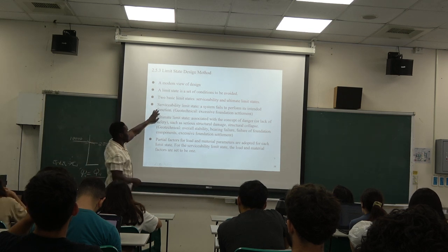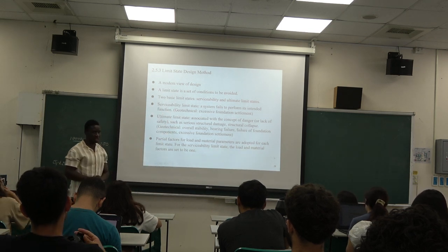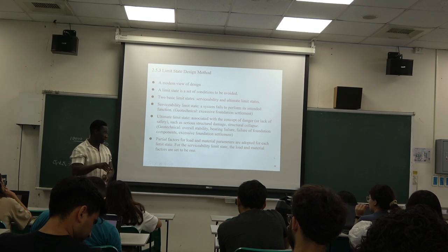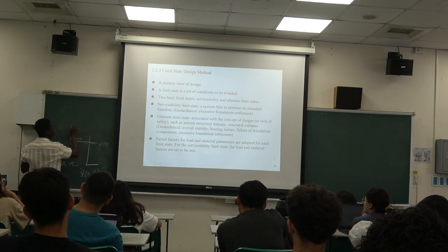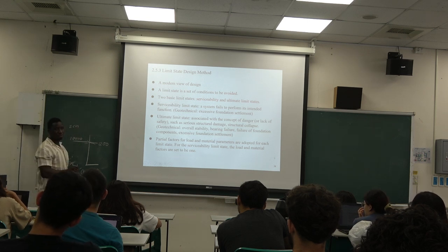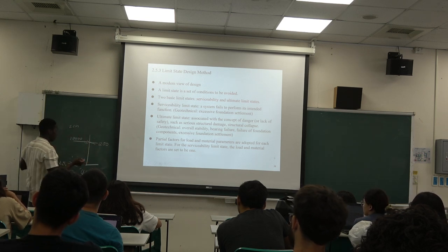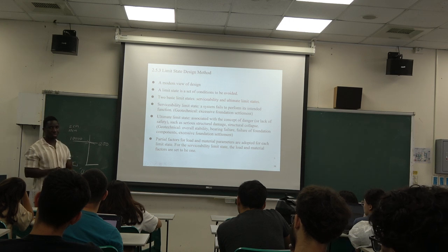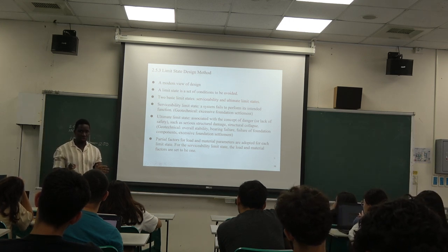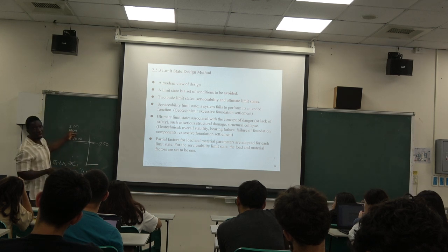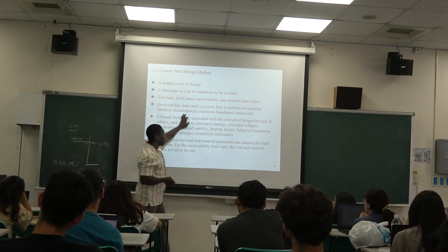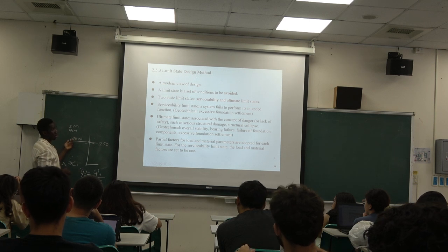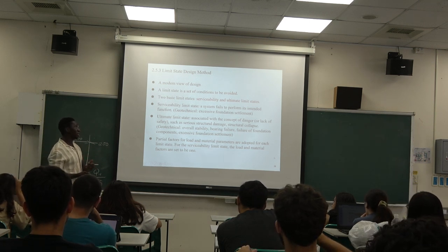Okay, so for the serviceability state, what happened? Our system fails to perform its intended purpose. So, for example, we design a foundation. The foundation is there, but the design settlement during our design was a maximum of 2 centimeters, let's assume. But after the design and everything, we start using the building, and then we have a settlement of maybe 10 centimeters. The building is still there, nothing happens to it, but we have this amount of settlement. So we have this excessive foundation settlement. We can still use it, but it doesn't fall within our design requirements. So it did not perform the intended purpose.